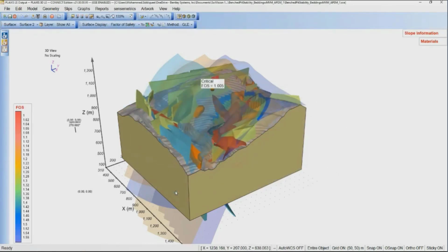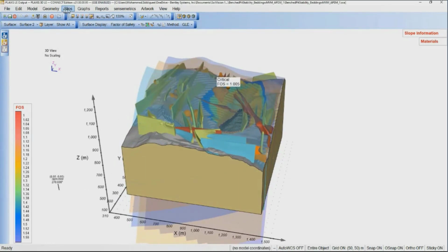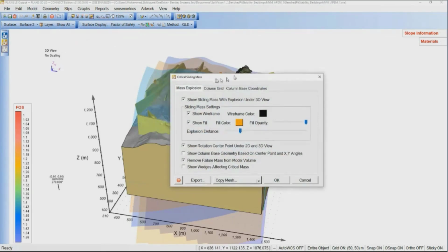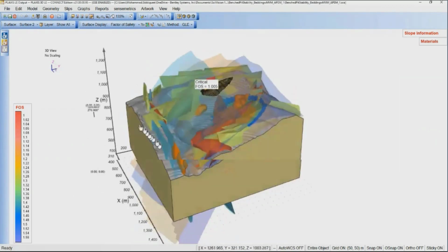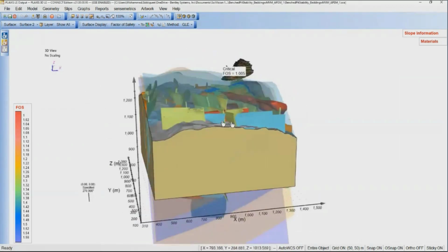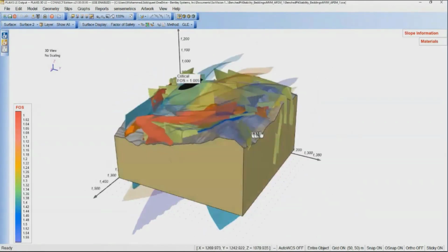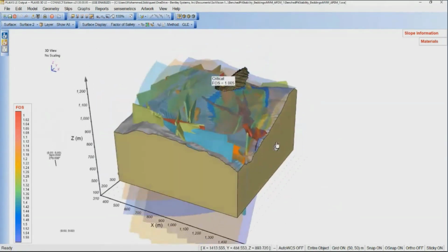And we can check this failure surface, whether it is same as before or something different, because that method is very fast. So how come it remains same? Let's check it out. Yeah, it is same, you can see. The surface is not ellipsoidal. That confirms that it is taking care of the anisotropy inside the bedding planes.